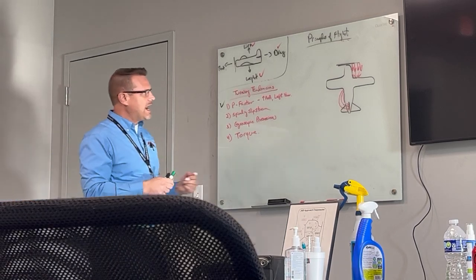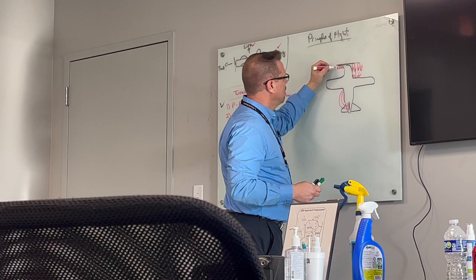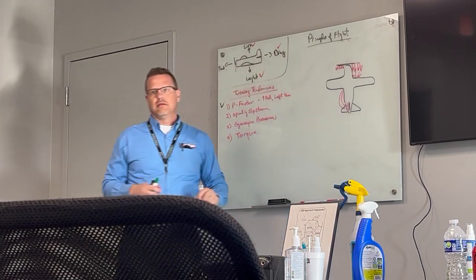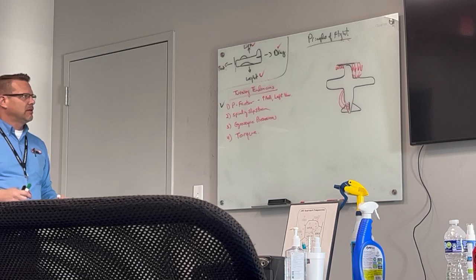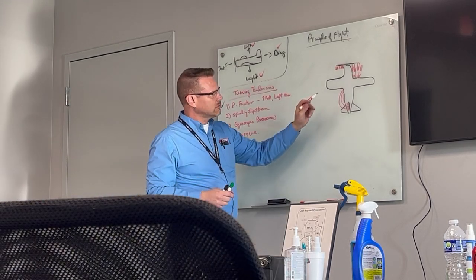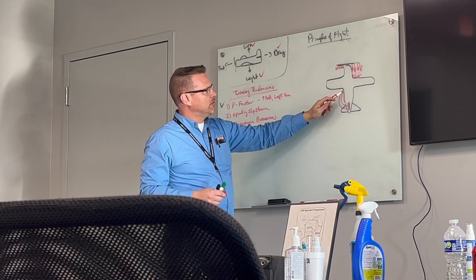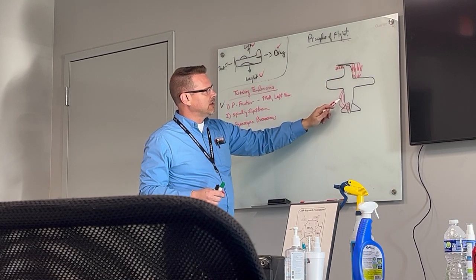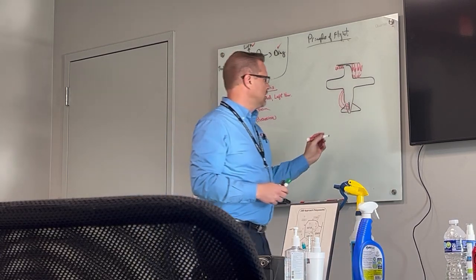Now, again, at high angles of attack, the left side would be generating a lot less thrust than the right side, and therefore most of the air coming down the right side of the body ends up moving underneath our body, coming up around the left side of the fuselage and hitting our vertical stabilizer on the left side.